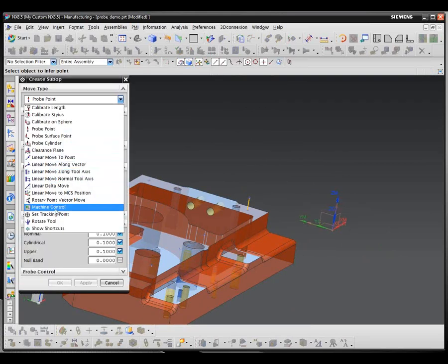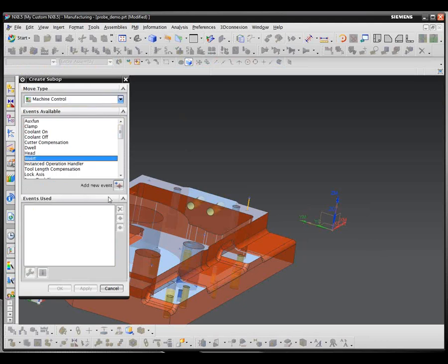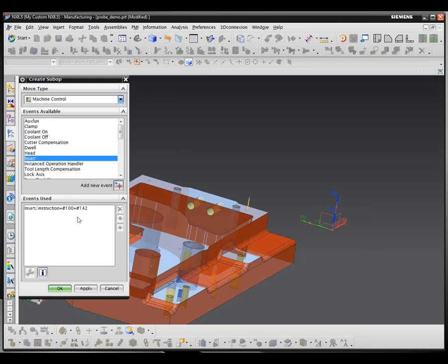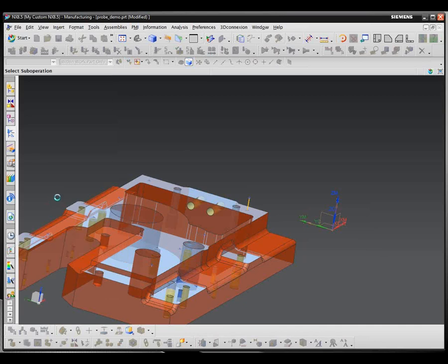And this time I'm going to add the machine control. Okay. And anytime you use a probe cycle, a Renishaw probe cycle, you need to do something with the output. And usually it's through a series of manipulating your variables. In this case, using a FANUC style, I'm going to use #100. I'm going to make that equal to #. Let's see. It helps to have a variable table. In the Renishaw programming book, they have variable tables, and so the variable I want is variable number 142. That's the z-axis error. And so my output comes out here. Hit OK.